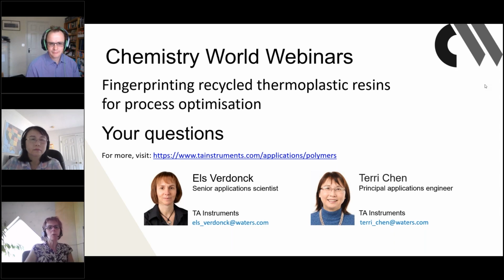Now, quite often when people want to study crystallization kinetics, they will not do that by doing cooling at different rates, but they will make isothermal experiments and check at different temperatures how long it takes before the material starts crystallizing. And you can then fit your DSC data to different models.